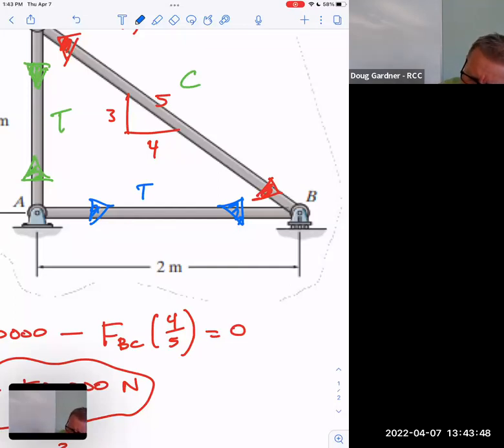But does it make sense? This would be required of that joint over there because the red's also pushing down and the blue's not going to help that. So that blue would have to be there. That force at B, there is going to be a force there. So the question is, is that going to smash into the concrete? Is that little connection going to break? Is the pin that it's on going to shear off? These are all things we still have to think about. That's what we're studying right now. Some of your questions in your assignment will ask about that pin. Will it shear off with this much weight being on it?